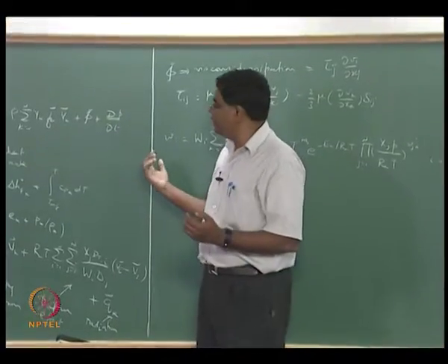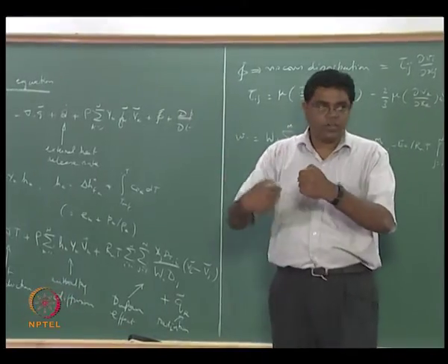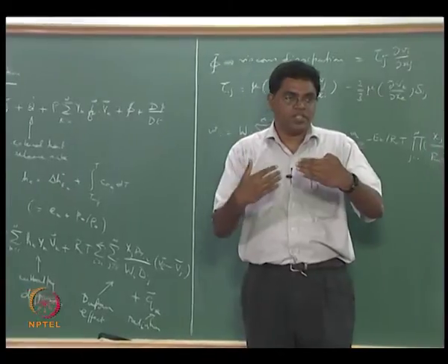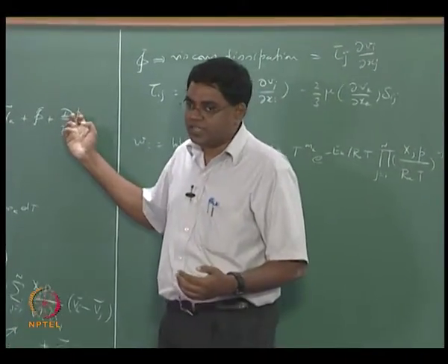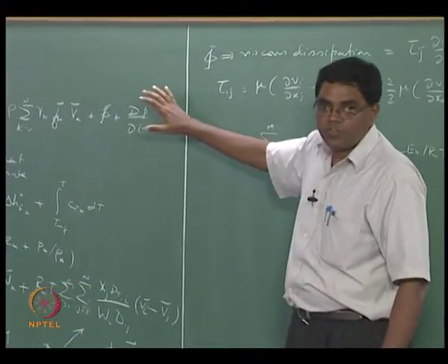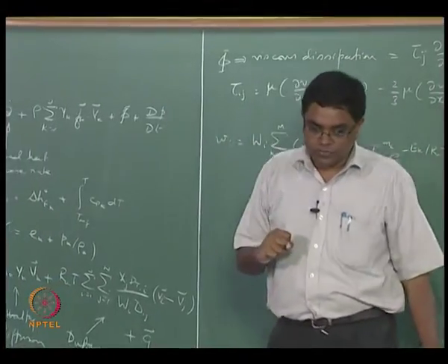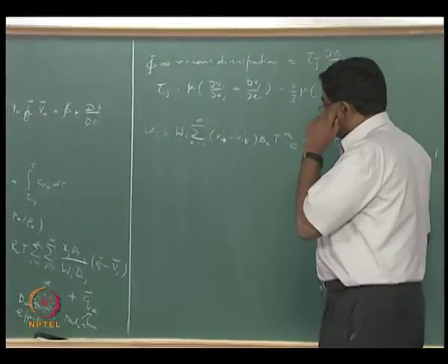There is pressure that is acting on a flow that is moving, and because the flow is moving, you now have a gradient in pressure that is acted upon by velocity. That's as if like you now have a pressure force that the flow is up against, and therefore you have a work that is done by that. And this is typically something that comes up for compressible flows. You don't have to worry about it in incompressible flows, alright. So this is the energy equation. Finally